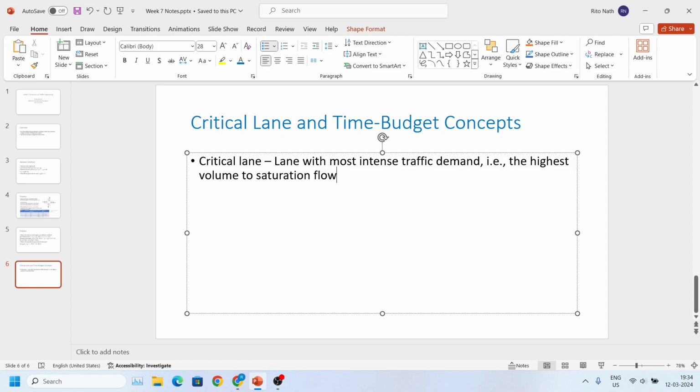So I think here also peak hour factor is relevant while discussing this. Here it's written that this is used to estimate the flow rate in the first 15-minute period of the peak hour. So whatever is given, you will divide it by this number.